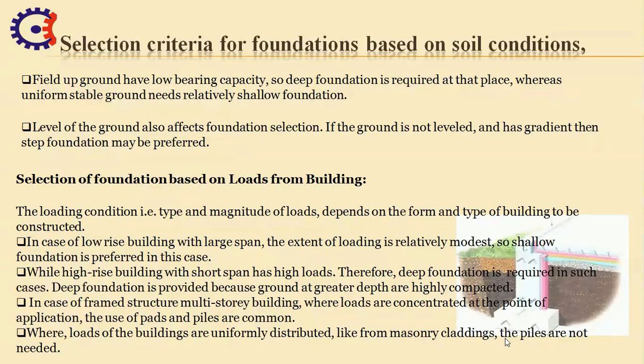For this we have to consider a minimum depth of 450 mm for a foundation if the area is prone to frost, so as to protect the foundation. Strip or trench base shall be kept above the groundwater table if possible.